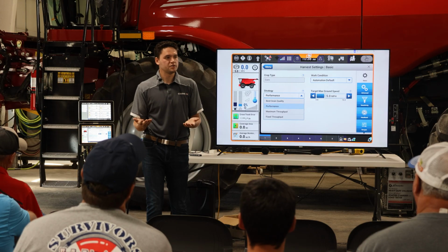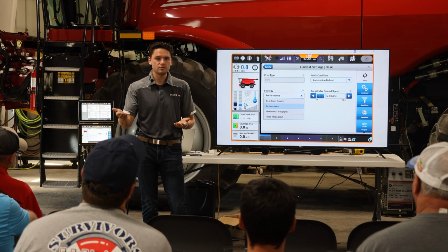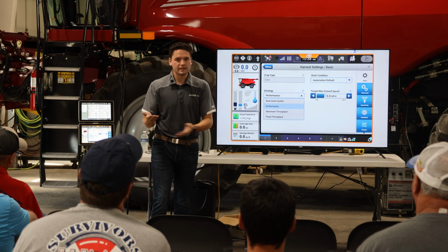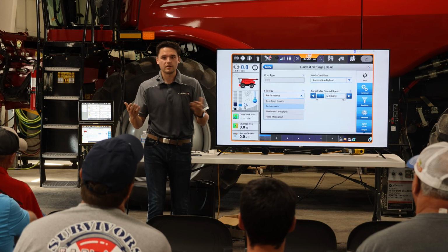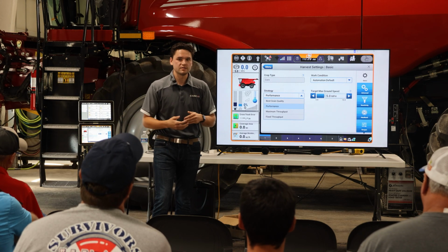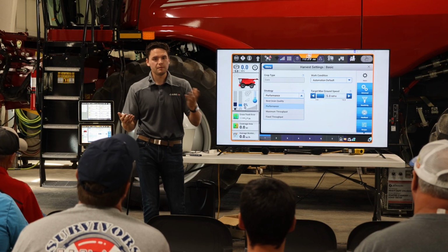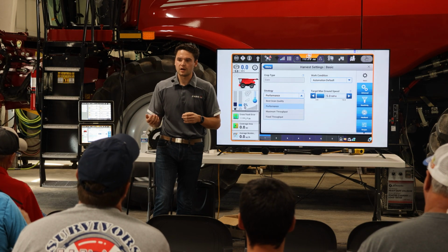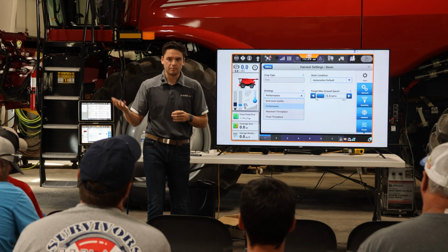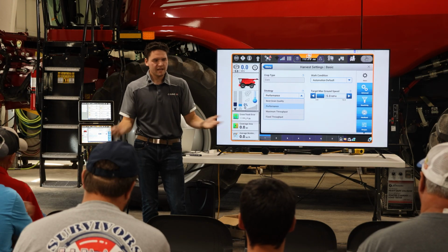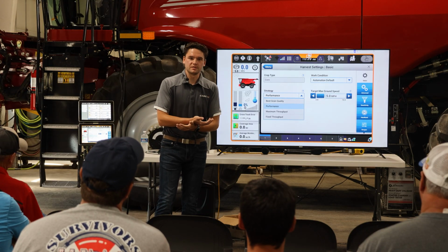With the best grain quality strategy selected, it will always choose to correct the MOG and accept a certain amount of losses, saying there are limiting factors because of this. So in some scenario, with best grain quality, it might be willing to accept a bit more sieve loss to maintain the tank sample. And the exact opposite can be said if we have performance selected.